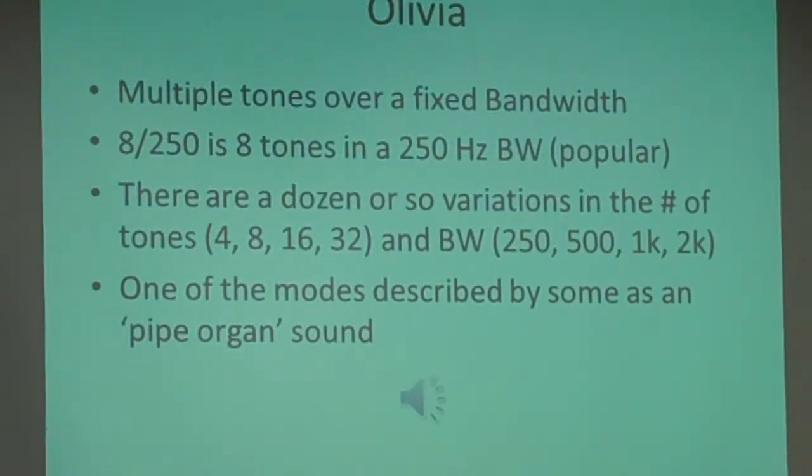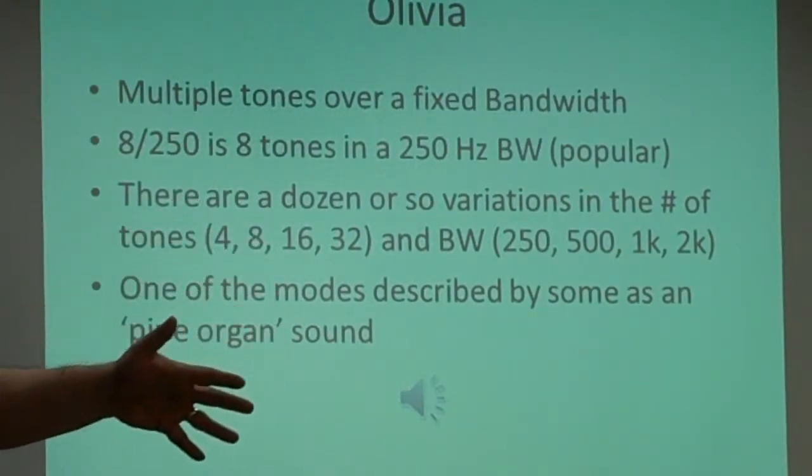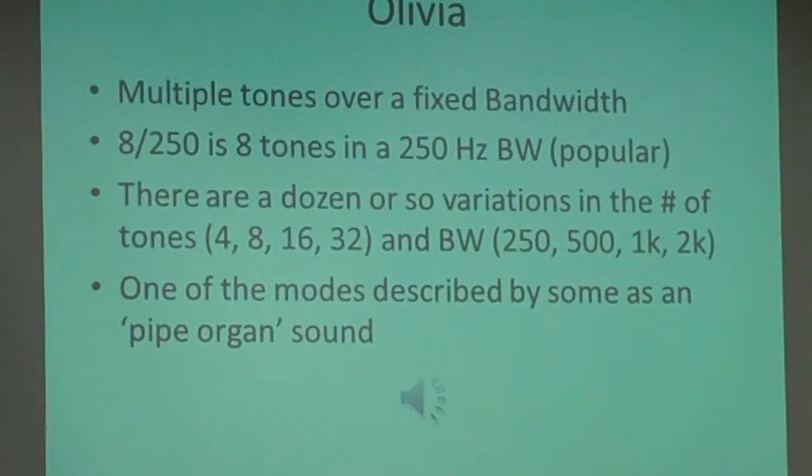The bandwidth also varies, somewhat proportionate to the number of tones used, of course, but it goes anywhere from 250 hertz all the way up to 2000 hertz. Obviously, with 2000 hertz on a waterfall, you're taking up everything. So you'd say, well, why would anybody do that?